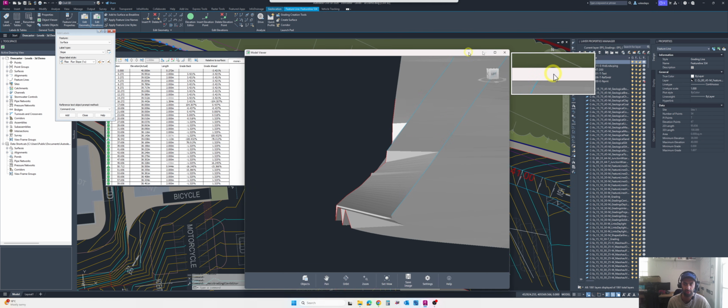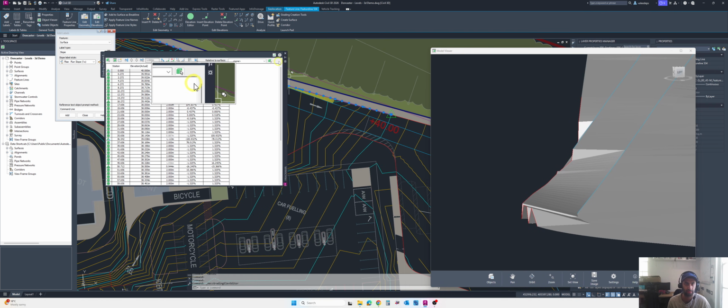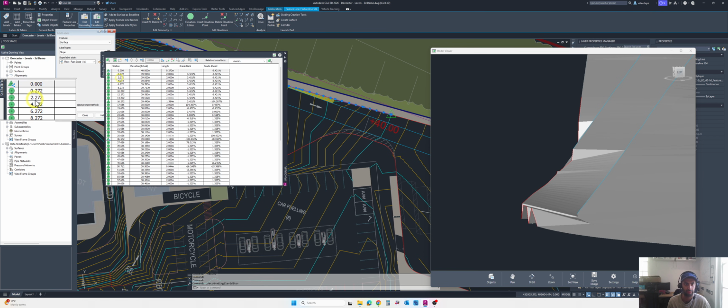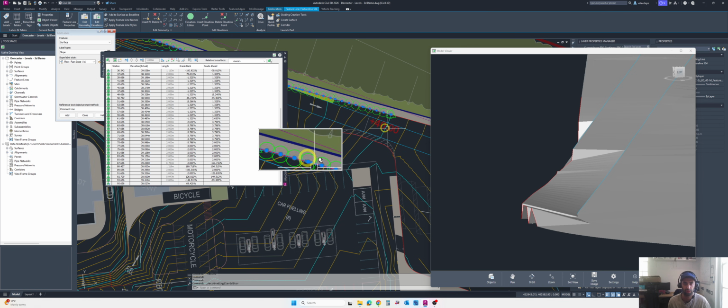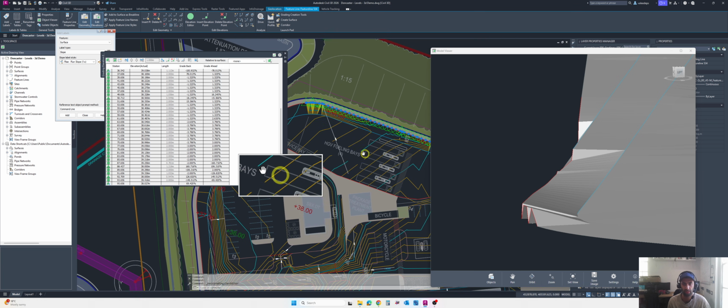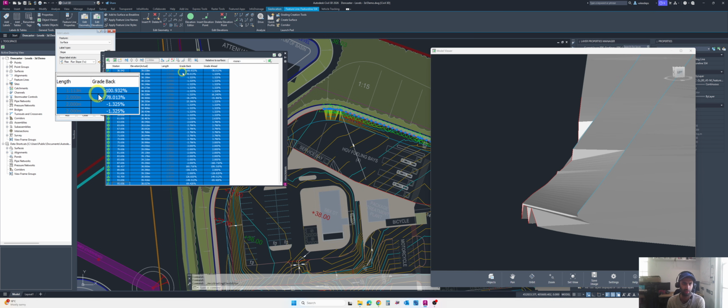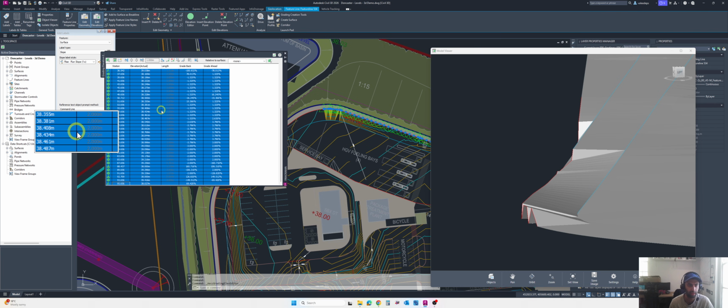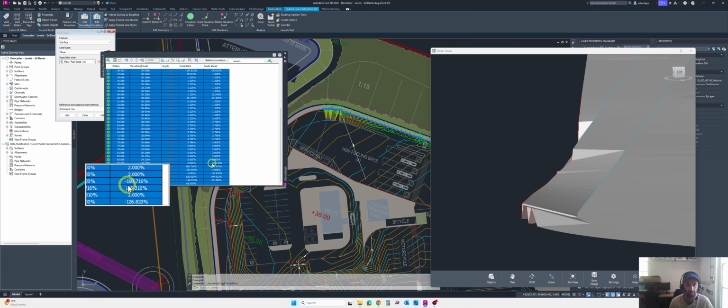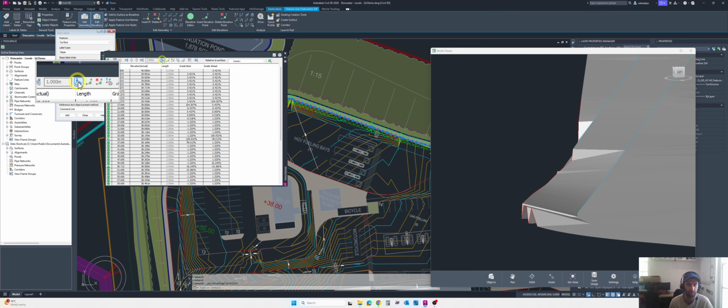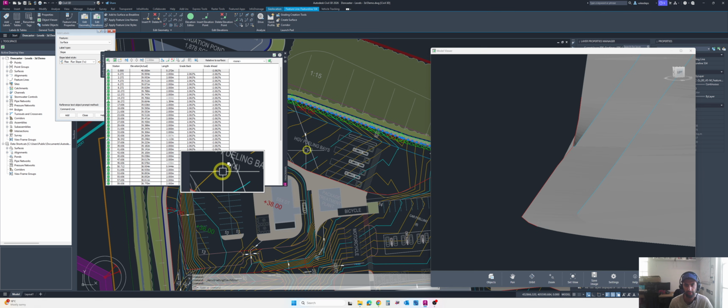Once we select all, this will select all of our points, and I want to grade in between. You can see this is like minus 100% grade, so it's not proper, and the last one again the grading is not fully well established. So let's say we can do a constant grade.